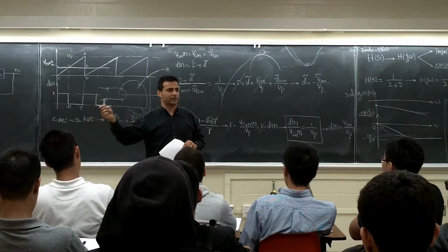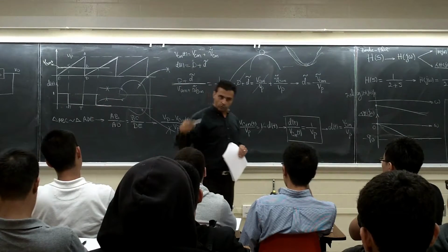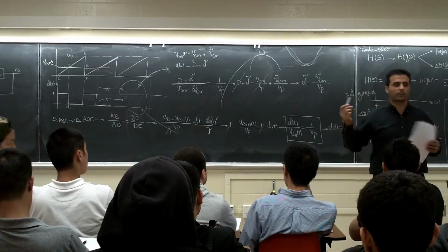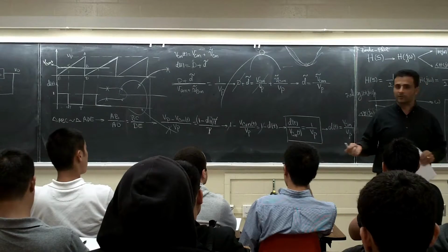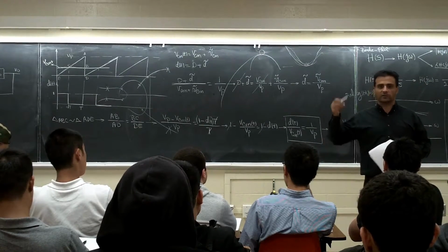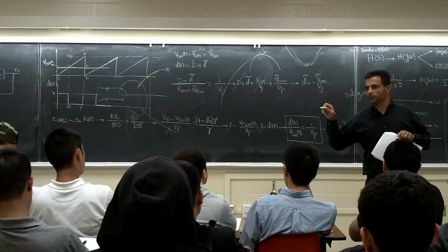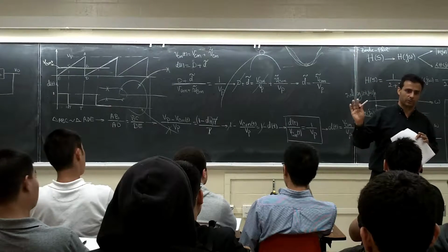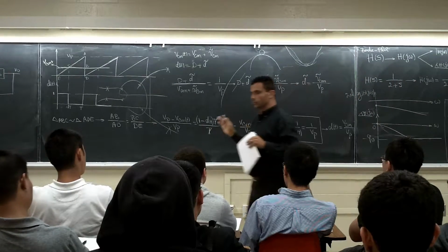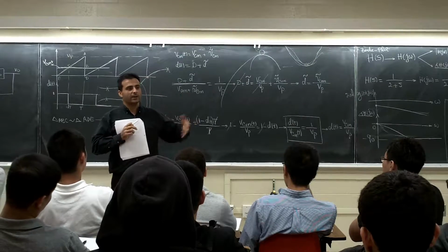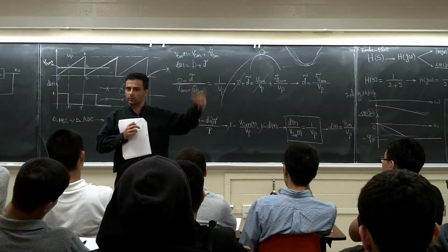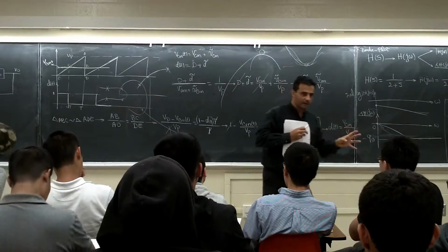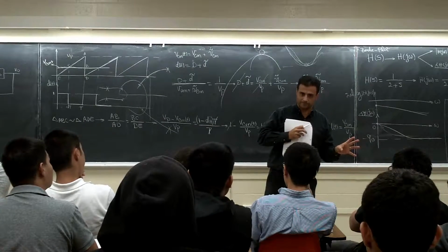I don't know, there's a tornado, for example. Look at the wind turbines, right? The wind is the input to the system. If wind is normal and you have a good system, the system is going to work. But think about it, if there's a tornado, we didn't design this one to work with a tornado, right? So the system parameters are going to go out of control. The protection system is going to come in, shut down the inverter, and they're going to have mechanical brakes to stop the turbine, to lock it, to not let it rotate, right? Because if they let it rotate, it's going to collapse. There is a limitation on how fast they can rotate. Every system has a protection, and the protection will come in when the control system cannot control the system.